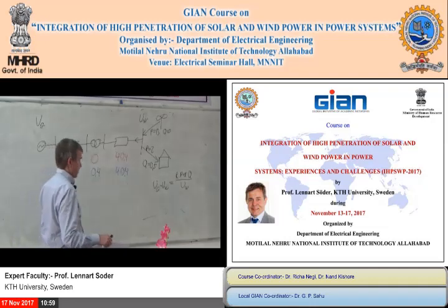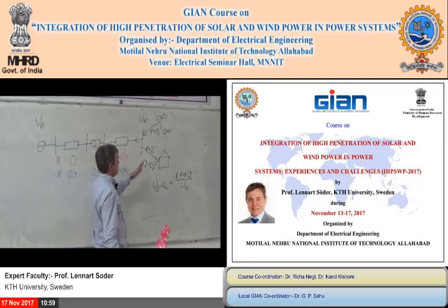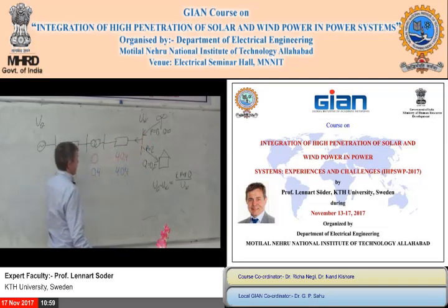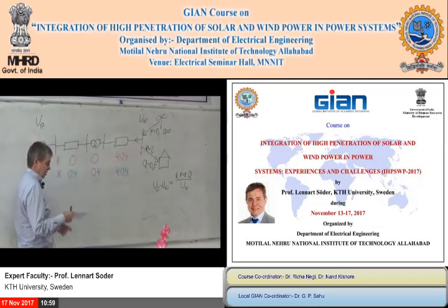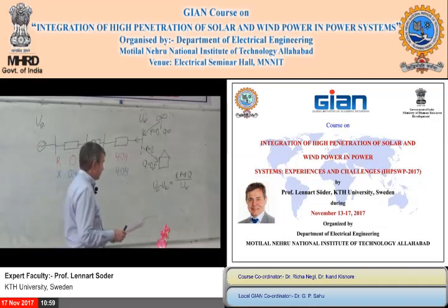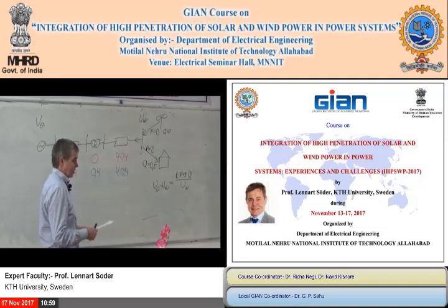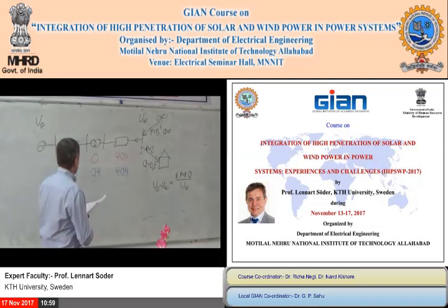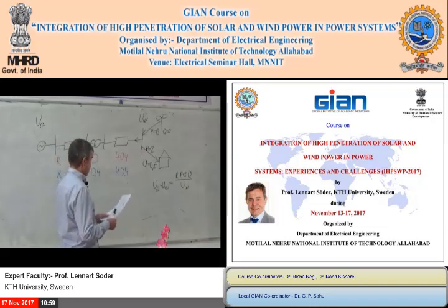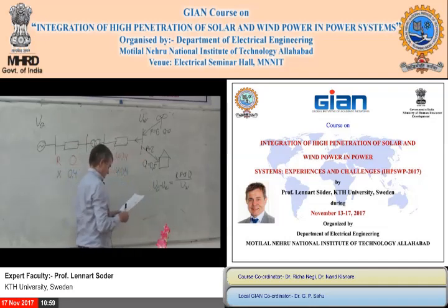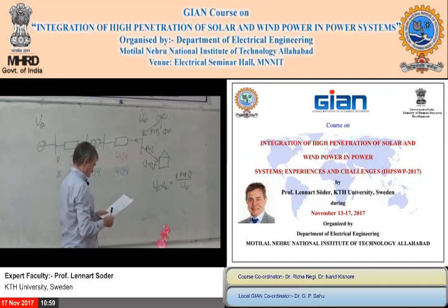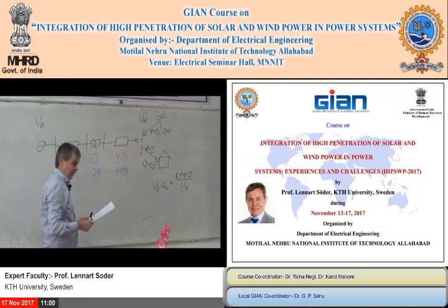Okay, the idea was that I studied the issues I had in the first two days. We discussed very much the voltage you have here, and then also the reactive in-feed you got from the grid. So I made some small examples, which I made yesterday. What you will see here is very much this R/X quota that I talked about a lot. The first question was: if we want to decrease the voltage, what is the most important, to change the wind power production or to change the reactive power in the wind power plant?